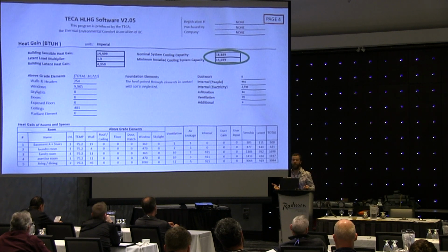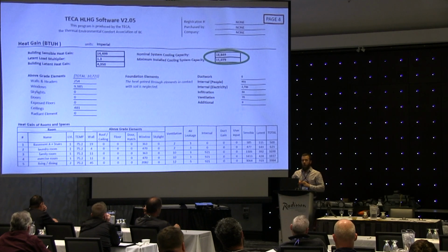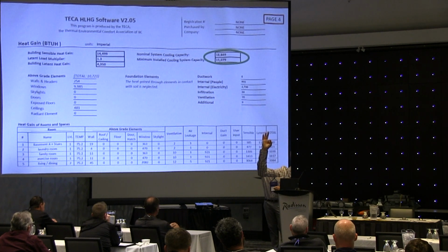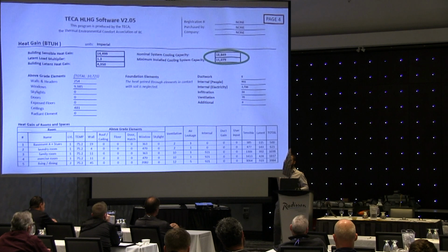And the reason that's relevant for us is because in the cooling season, our load is to take heat out of the air, right? We want to cool down the air. There's heat in the air that we want to remove. That's where our load is. The more heat in the air, the harder we have to work to remove all that heat. But there's also moisture in the air, right? Energy has been spent to turn that water into vapor. So it's sitting in the air as this energized piece of gas, basically. And as I lower the temperature of the air, I need to cool that little piece of gas to get it to turn into water.